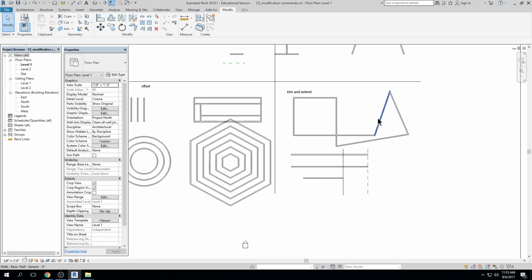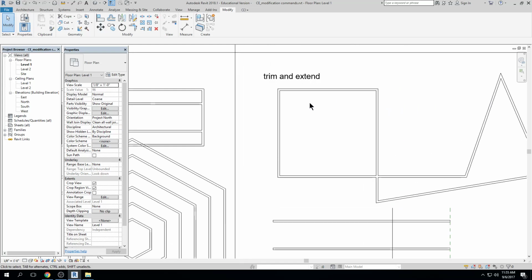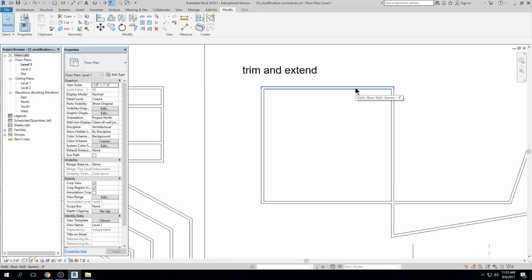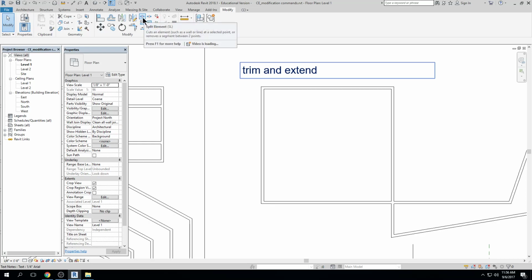Okay. And I'll show you throughout the semester where the appropriate use of each one is and why you would use them. But this is essentially the same command as break in AutoCAD, where you want to take a line geometry and you want to cut it, right? You want to create a break so that you can change the layer or delete half of it or do something to that line, right? And the same applies in Revit, where maybe half the wall is brick and half the wall is CMU, right? We want to be able to break it or split it in Revit to perform different operations on the different walls, okay? So split is right here, SL, and split with a gap, okay?